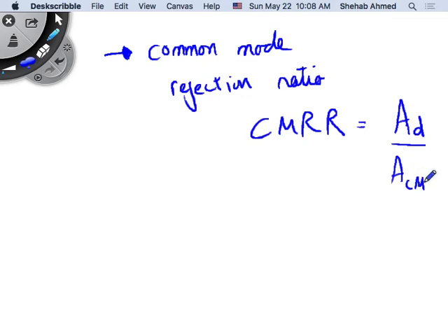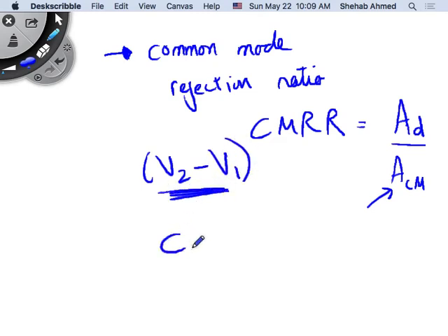There is some common mode signal that we drew before. If this common mode signal passes through with a gain, that means I'm amplifying the common mode signal. What I would like is to only amplify the differential signal. V common mode is my common mode signal.